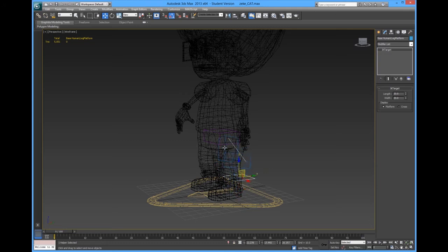That's called an IK, or the process is called inverse kinematics. It works out that if I pull this up, the leg is going to bend in a certain place. As you can see there, it calculates the angle. It also calculates how limbs would react, so the twisting. If you don't put the bends in correctly though, it will do very, very strange things.